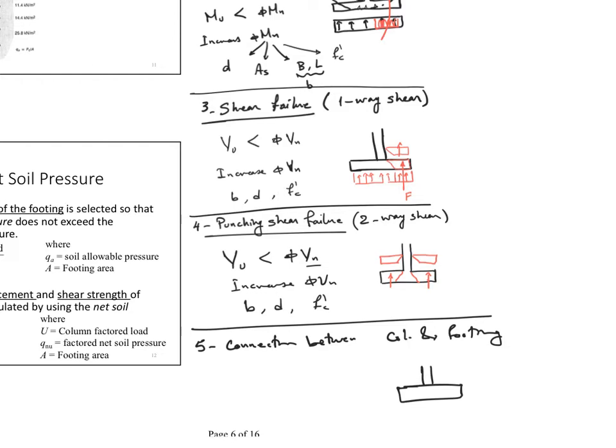The reinforcement here coming from down here is different than the one up here, and two different f'c's and bearing of column on footing. So there might be something that happens here. And what you need to make sure is that your Pu is less than your P bearing at the connection, right? So those are 5 limit states.